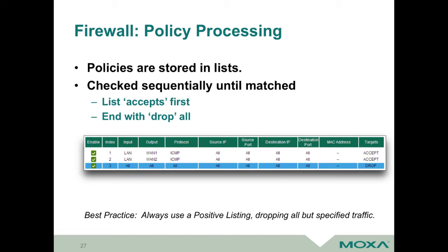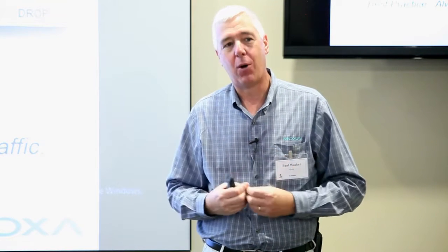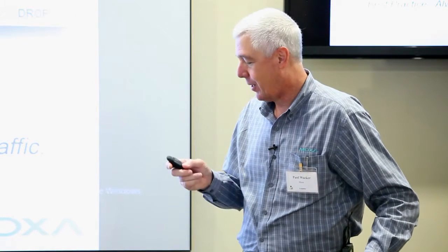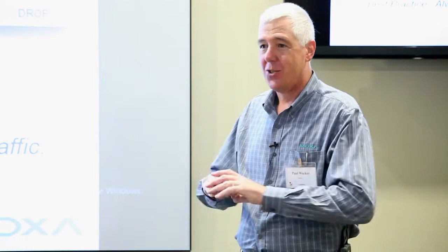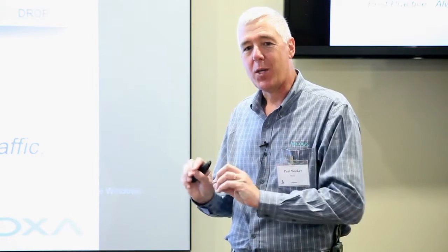However, if you have a SCADA system that's doing Modbus TCP, port 502 is used for communications, so you might want to add a rule that allows incoming requests on port 502 to see what's happening at that site. So I think you get to see a little bit the power of what you can do with firewalls to control traffic, at that high level. Again, deny everything and only allow what you want to come in.